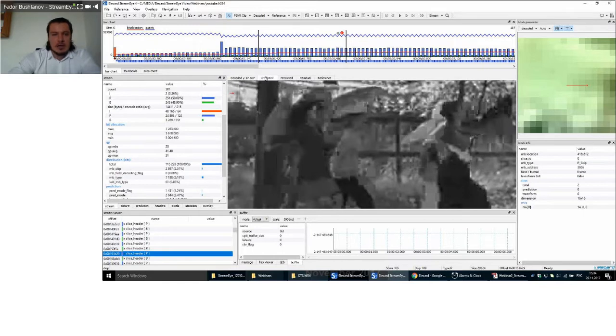What we will receive is the unfiltered picture. The difference between unfiltered and decoded is that we apply a deblocking filter to the unfiltered picture. Looking at the unfiltered picture, you may notice a blocking effect. You clearly see the borders of all macroblocks on the picture.